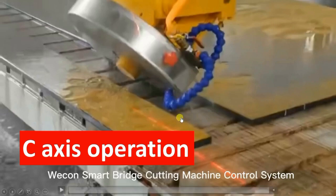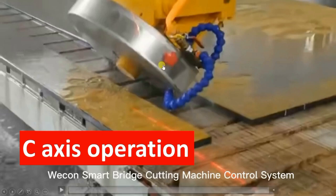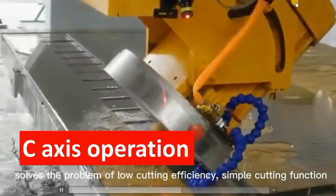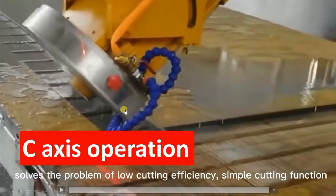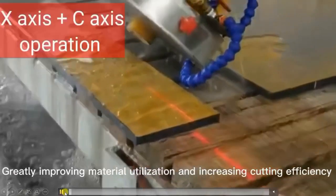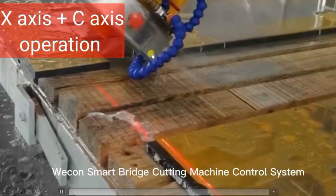We will understand the C axis operation. Here you can see the cutting wheel is completely vertical or perpendicular to this plane. But here you can see the cutting wheel is slanted. So this is the operation of the C axis. You can see the complete motor is slanted and it is moving forward. So this is the movement of C axis. Here it is coming in X direction and also C axis is operated.